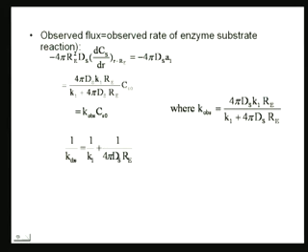I am not sure if you have done such an example before, where you have done examples where two mass transfer resistances or two heat transfer resistances are in series, but I am not sure if you have done a case where one heat transfer resistance or one mass transfer resistance is coupled with a reactive resistance. If you have, then it is an interesting thing. Otherwise, this is one of the examples of resistances in series, but the only difference is that the resistances we are considering are not necessarily of the same type. So, you have a reactive resistance and a mass transfer resistance, and you are adding them up to get your total resistance.